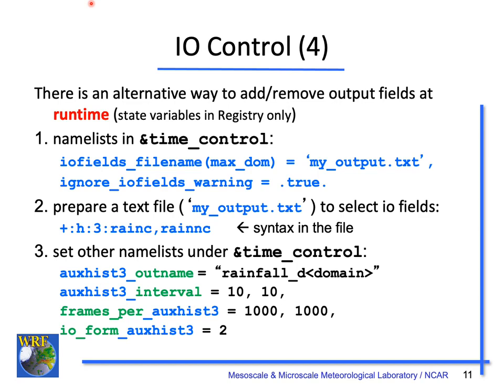While this option is certainly convenient, a caveat is that it is not efficient for production runs. For production runs, it is best to modify the registry file, compile it once, and then use it in your production runs. We will save computer time using the registry file method.